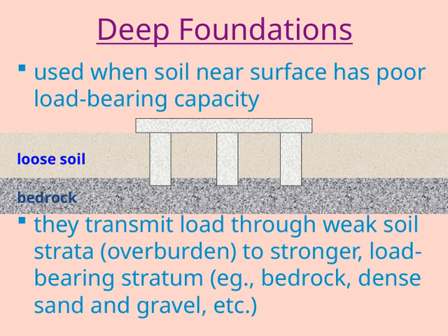All right, let's talk about deep foundations. These are used particularly when the soil near the surface doesn't have enough load-bearing capacity to support a structure. Instead of relying on the weak surface soil, deep foundations transmit the load downward. They do this by transferring the load through the weaker soil layers, often called overburden, down to a stronger, more stable layer beneath. This stronger layer could be bedrock or dense sand and gravel, which can safely carry the weight of the structure. So, in essence, deep foundations act like a bridge, passing the load through the weaker soil to a more reliable support beneath.